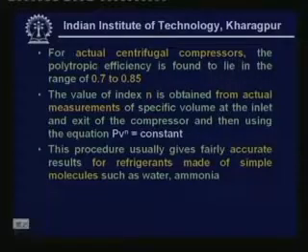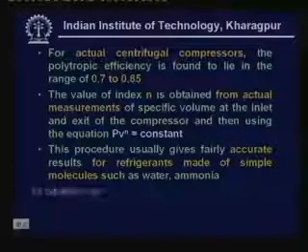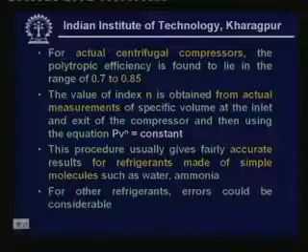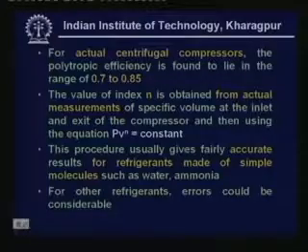This procedure usually gives fairly accurate results for refrigerants made of simple molecules such as water or ammonia. For other refrigerants, errors could be considerable. So this procedure and the expression for polytropic efficiency is not a 100% correct method, and it does not give you 100% correct values.